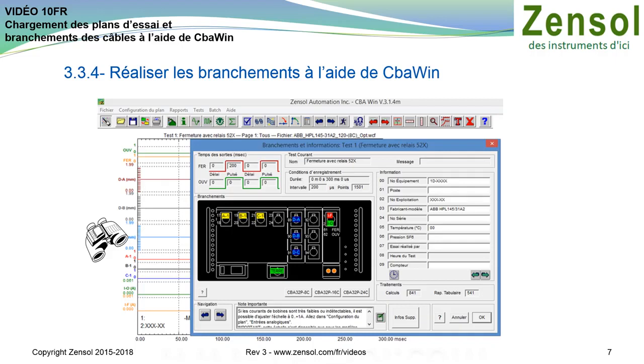In this example, we can see that 3 contact cables need to be connected to the first 3 contact inputs. Connect only the yellow clamps to activate only signals 17, 19, and 21. Only the first 3 optical encoders are activated, signals 89, 90, and 91. The optical encoders must therefore be connected to these inputs. At the bottom, read the important notes.